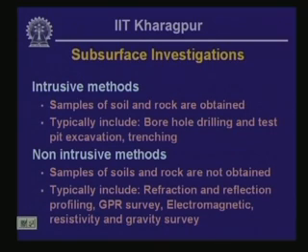Alternatively, subsurface investigations could also include non-intrusive methods in which no borehole is drilled or test pit excavated through the geologic units. In these testing procedures, samples of soils and rocks are not obtained, and typically these procedures include refraction and reflection survey.